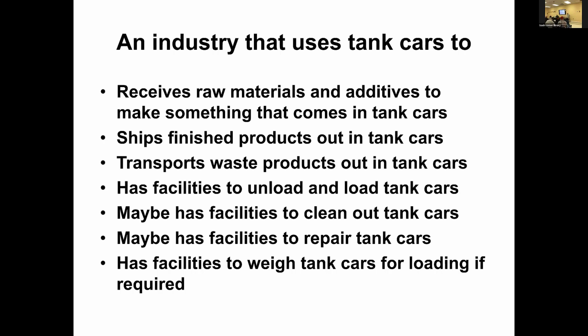And again, we have to weigh them. And so I got some cars, we have the outage, we can fill to a certain point, and that's as much as we put in. Other cars, we have to weigh for the product that's going in, because again, you don't want to open a car, chlorine, up to the community, but instead you're going to scale it and weigh it. And if you're doing LP gas and stuff, then you actually have a gauging device on top that floats on the liquid and gas is above it to measure how much product you have in a car.